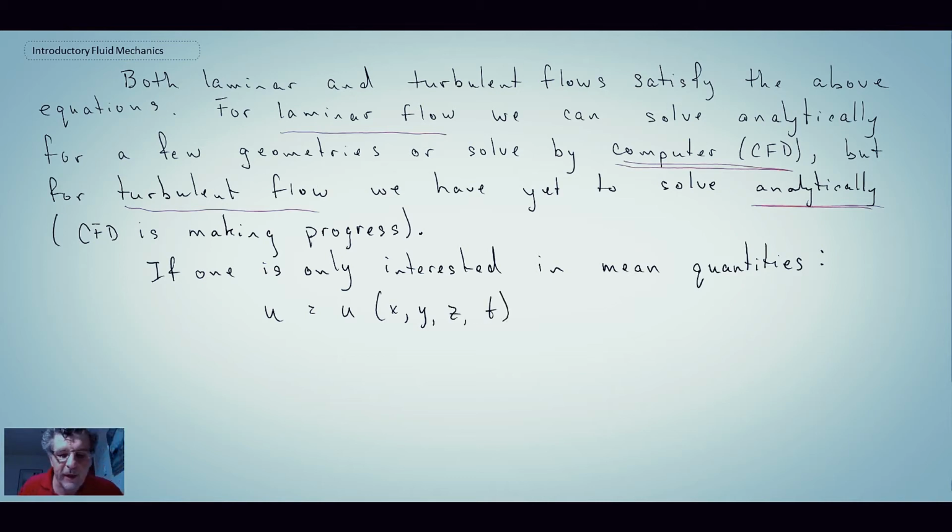So when we're dealing with turbulence, the velocity is going to be a function of the three spatial dimensions as well as time. And quite often we express velocity as a time average quantity. A lot of the different parameters that we look at, velocity, pressure, things like that, go through this process. The time average is taken over some period of time over which we collect velocity data, and then we do a time average of it.